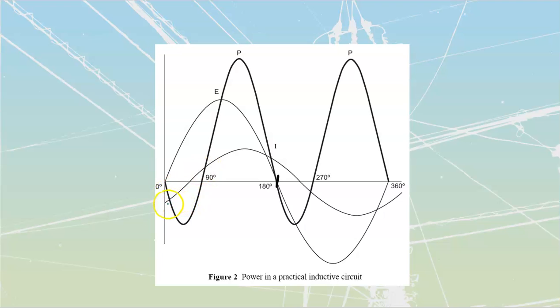I'm going to highlight over top of these, because what's fun with this pen is that I can actually pick up and move some of these components. This over here would be a truly, purely resistive circuit. If I have that green line right over there, that would be truly resistive. If I go more and more inductive, it starts to move over. If I increase the amount of inductance, it would move over even further, until eventually I would get to that 90 degrees, which would be the maximum theoretical inductance. We'll never achieve it, but we can get pretty dang close.